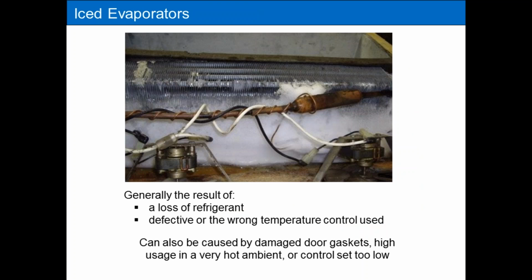All right, let's talk about iced evaporators. Pretty common problem. Iced evaporators could be caused by several different reasons. Loss of refrigerant can cause an evaporator to ice up. A defective temperature control can equally cause it to ice up.